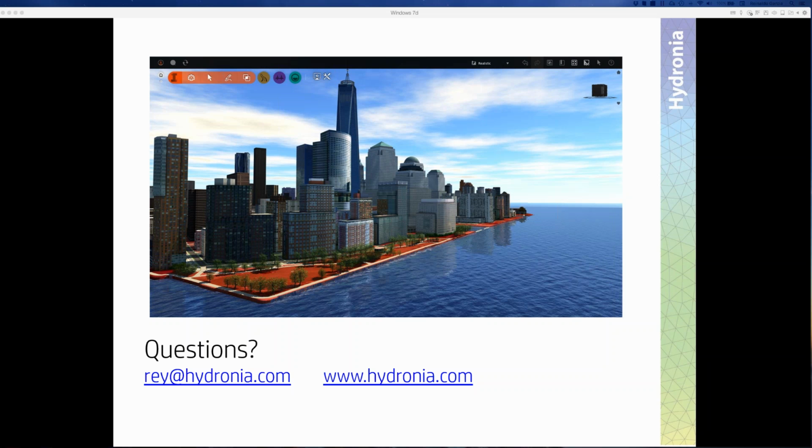You can also create a data set that is just an assumption. If you don't have any better data, you can assume a certain depth and then create a scattered data set that reduces the bed elevation only on the river, and then you have a new scattered data set for that. There are many tools to do that. I just mentioned two of them.